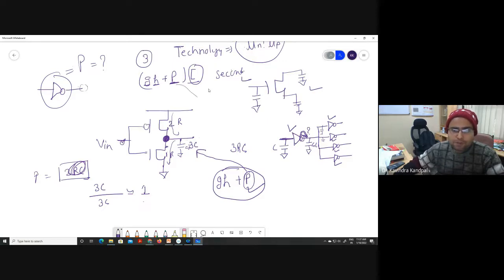If you put P equal to 3RC, what is going to be the unit? The unit is going to be second multiplied by second, and everything will be messed up, right? So in order to make it consistent with the linear delay model, the parasitic delay of this inverter is normalized against the input capacitance. If the output capacitance here happens to be 3C, this is divided by the input capacitance, again 3C. This is my parasitic delay of an inverter, P inverter, which is closely equal to 1.